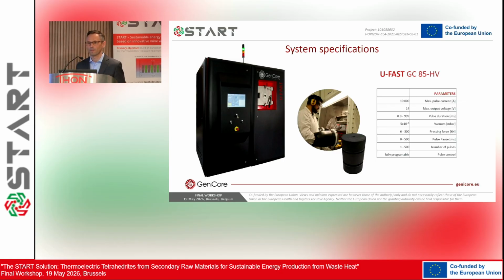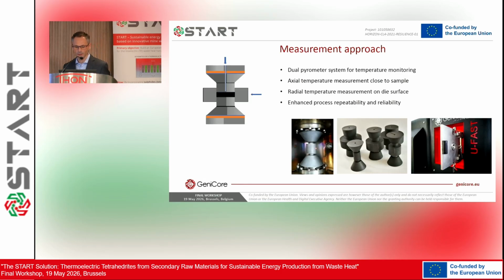But at the production stage, we base on a previously generated recipe, and the machine automatically conducts the whole sintering process. It means that the only task for the operator is to put the graphite set into the vacuum chamber and press the start button, and in parallel spend time on assembling the next set.